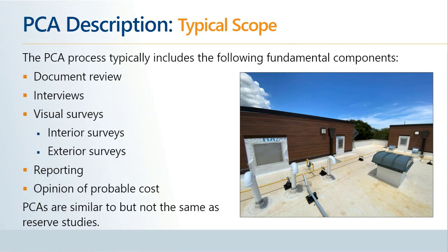More often than not, there are some documents provided by the seller. The review is based on whatever documents are provided. It may include original construction documents, previous reporting of prior assessments or evaluations, even previous repair records. The aim of the document review period is to enhance the reviewer's understanding of the asset, its performance at present, as well as its repair and maintenance history.